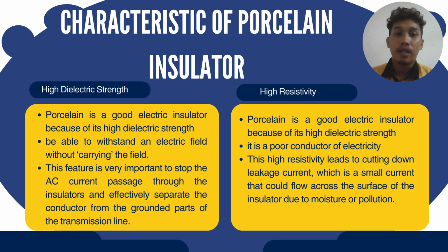And we go to the next characteristic, which is high resistivity. Porcelain is a poor conductor of electricity, and this high resistivity leads to cutting down leakage current, which is a small current that could flow across the surface of the insulator due to moisture or pollution.